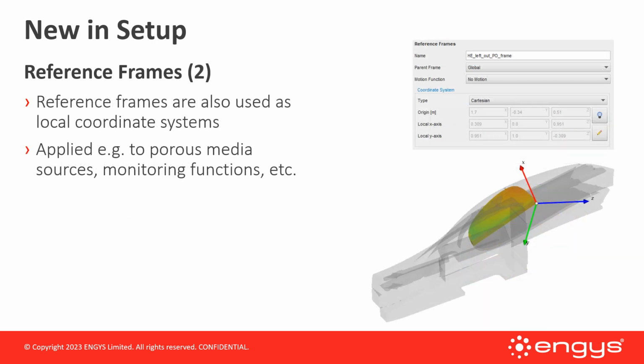As I said in the previous slide, a new method for defining local coordinate systems and body motion has been added with reference frames. Very useful applications can be, for instance, porous media, thermal sources, monitoring functions, and other post-processing tools.